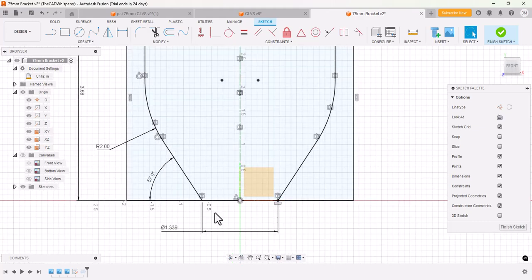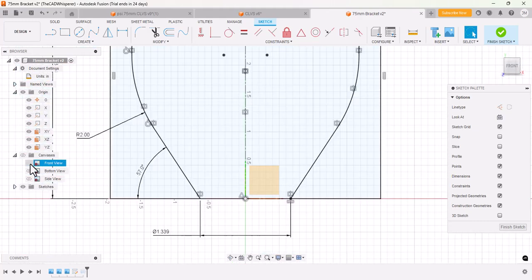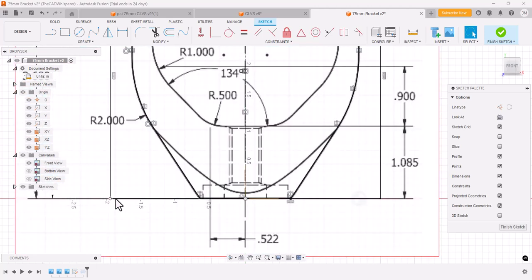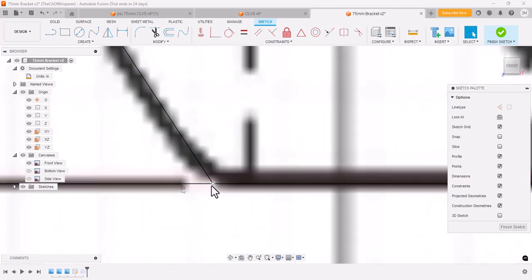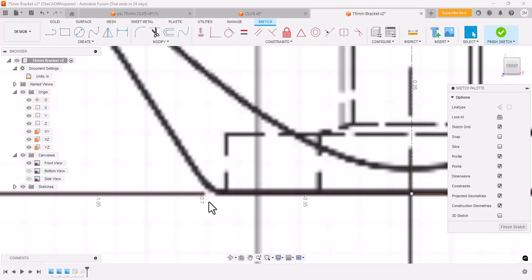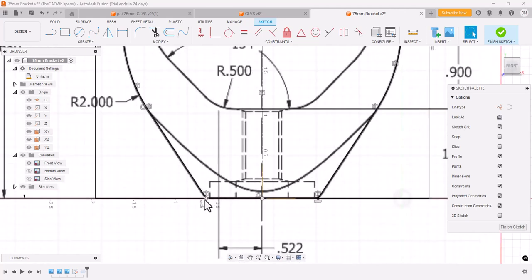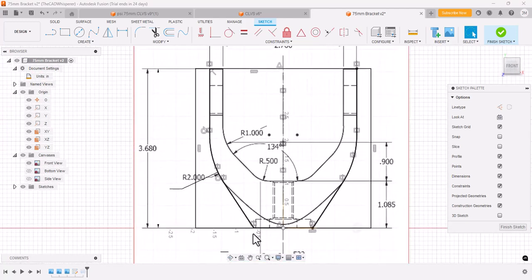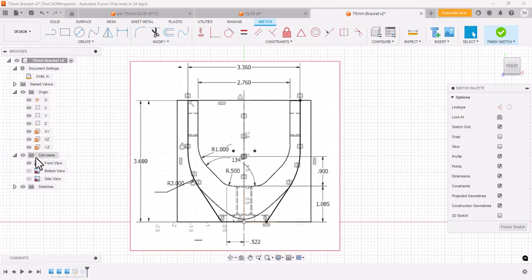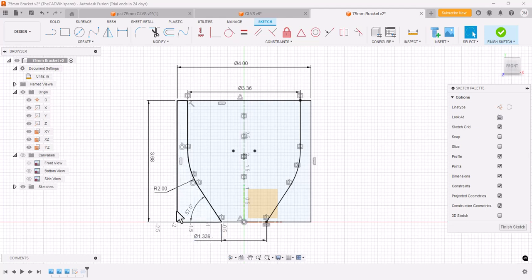Then keep in mind that when we machine this, that point that we just dimensioned is where this arc will come down and meet this line. So that point is going to be machined away, and we may create an operation sheet where that is a starting dimension, because after we machine that and put that fillet in there, we can no longer measure that dimension out on the shop floor or in inspection. So we need to keep those kinds of things in mind as we are putting in our sketch dimensions.